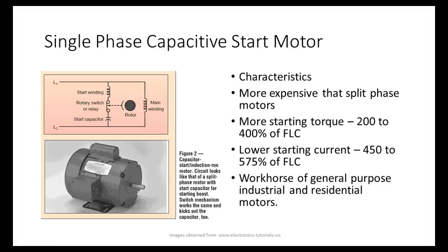Now a lot of motors, especially in HVAC systems, the capacitor won't be mounted on the motor; it'll be mounted somewhere else. So a lot of motors have external start capacitors. Your air conditioning system will have an external start capacitor. There will be two wires coming out of the motor, and they go to the start capacitor.